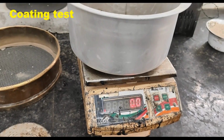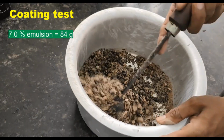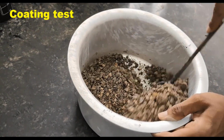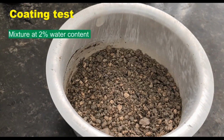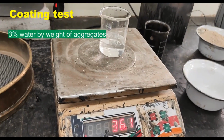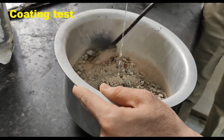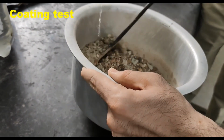Now add the amount of emulsified asphalt as determined from the equation, 7% in this case. Again, mix it properly, and here also 1 minute mixing time is sufficient. Now this is the mixture at 2% water content. Similarly, you prepare the mixture at 3% water content and 4% water content, but the amount of emulsion will remain the same, that is 7% by weight of aggregate.